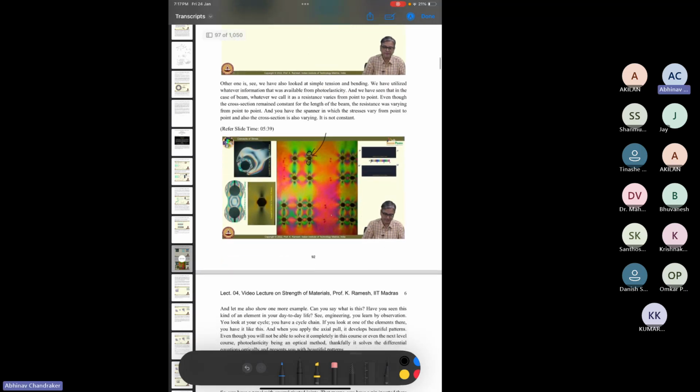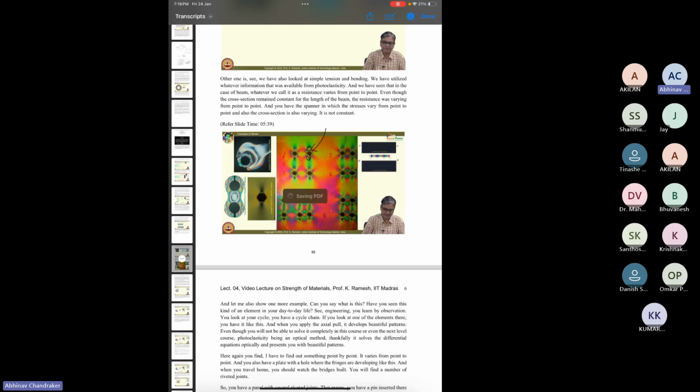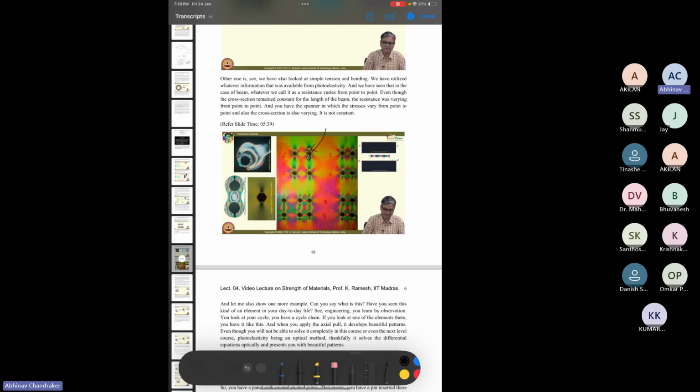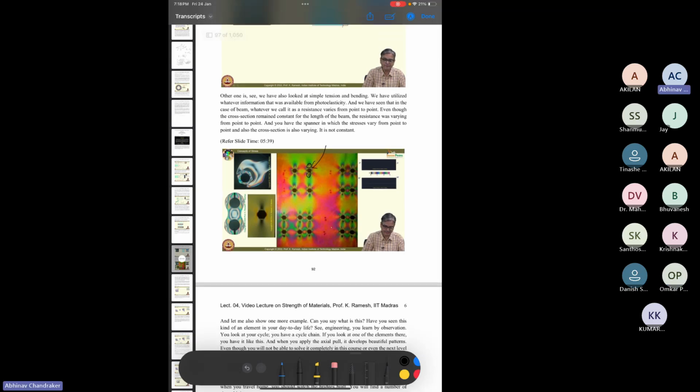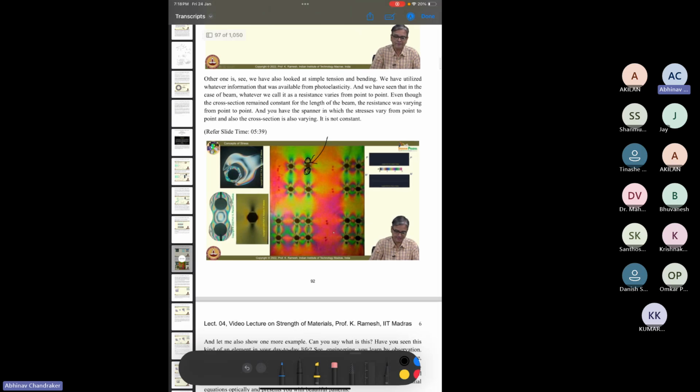But this is how most of the components we use actually are, because we need to use holes for inner components so that we can apply loads to them, right? We cannot join material directly so easily. So if you have these kinds of components, you'll have some high concentration stresses near those load application areas. And we would like to know how much the stress values are, so that we can estimate till what load we can use that component and when it might fail.